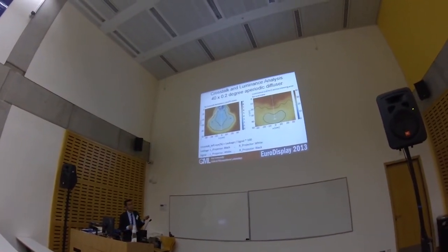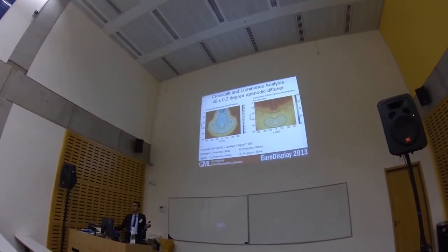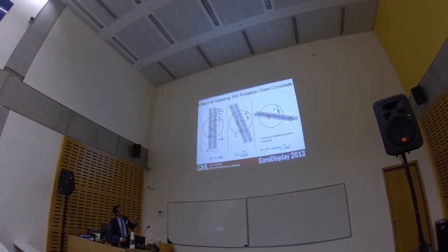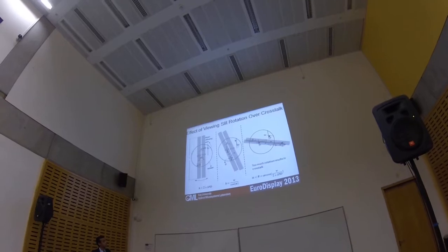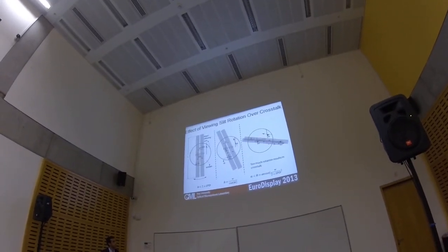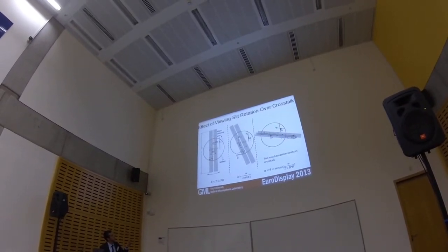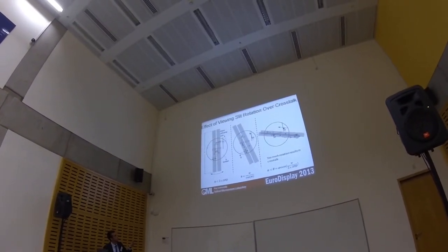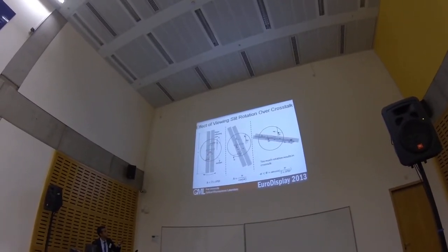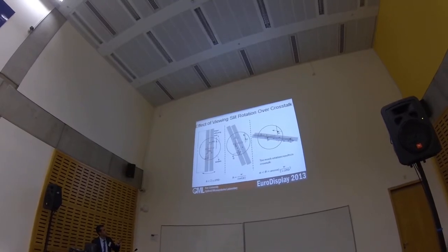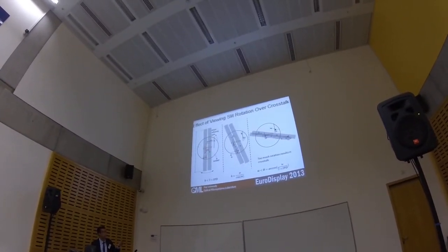But what if we want to reduce the crosstalk values, or we want to have a larger weaving area? This is the effect of weaving slit rotation over crosstalk. So now I will come to the crosstalk analysis again. As you see here, the crosstalk increases when the width of the weaving slit increases, because when the width is so large, light will come through to the other eye, so it will leak more and the crosstalk will increase.